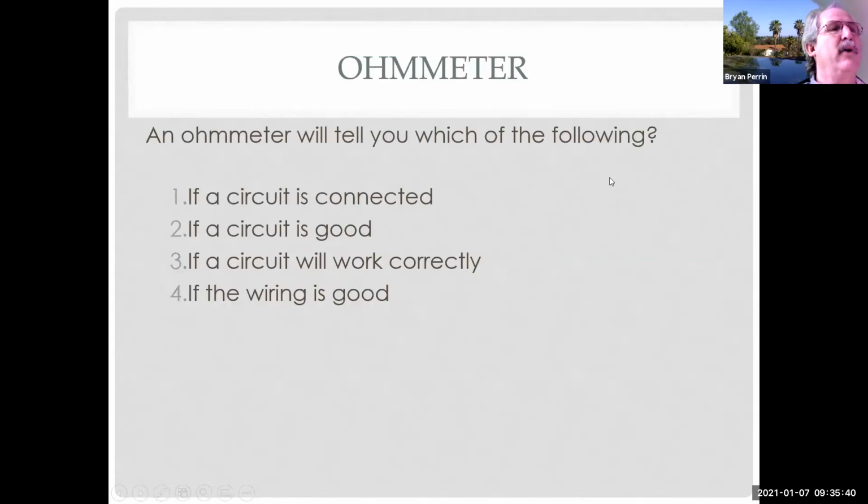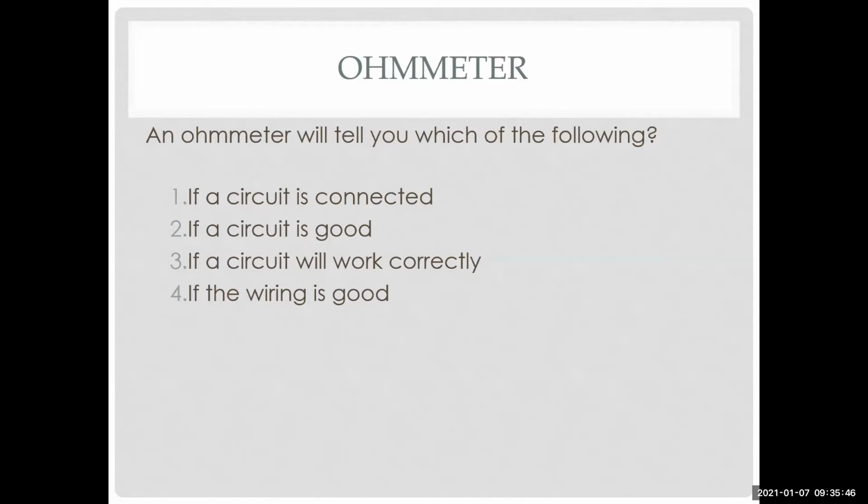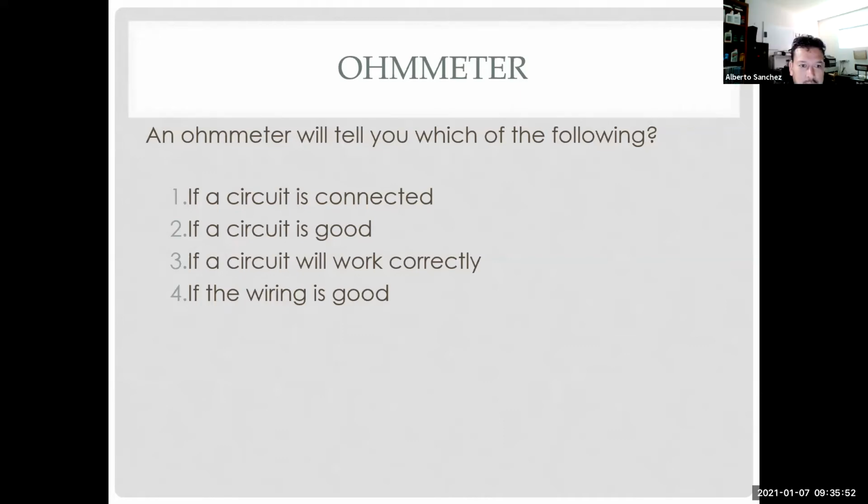So an ohm meter will tell you which of the following? Number one. Yeah, number one. That's it. I don't care what the book says. I don't care what anything else is. All it tells you is that it's connected, period. It doesn't tell you it's good. It doesn't tell you it'll work correctly. It doesn't tell you that it's good or that it'll work. It just tells you it's connected. And that's a real important distinction.